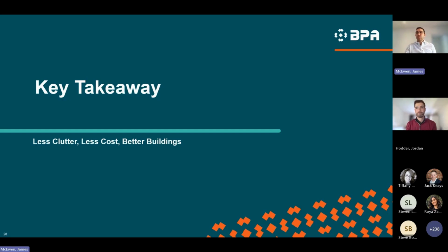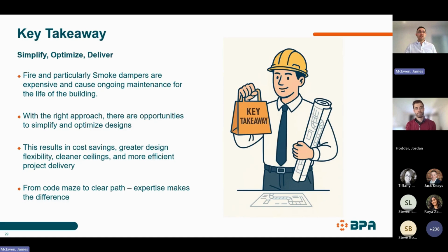So we're hoping the takeaway here is that the rules are a little bit complicated. There's some nuance to it, but there's actually a lot of scenarios where smoke dampers aren't required if you look at things closely. And for us, the best way to get that information and review it is by using the fire life safety diagram drawings that are on projects. Or if it's a small project and you don't really have fire life safety diagrams or you don't need them, then indicating what the occupancy of the space might be or where public corridors might be right on the plans, so that we can see where all those things are to help us make the right choice.